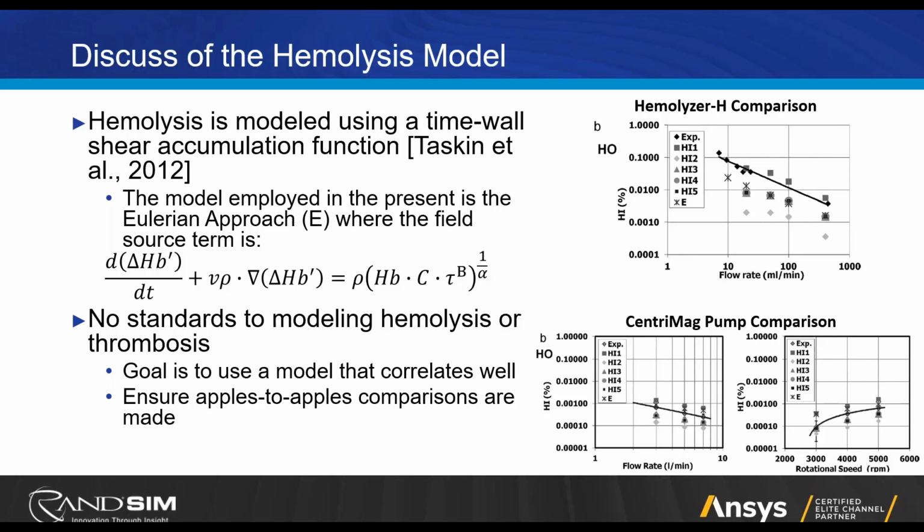And these models can all be implemented into optimization studies. So instead of just looking at physical characteristics of the flow, like pressure differential, flow rates, and shear stresses, we can also implement the hemolysis levels into our optimization study, saying that maybe we want to minimize torque, but we also want to minimize the hemolysis index produced by our pump. These are all just additional tools within your tool belt, and they're all made possible by leveraging CFD early on in the process.